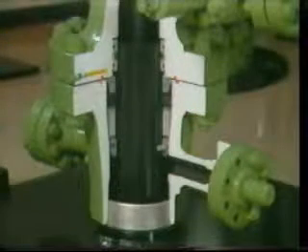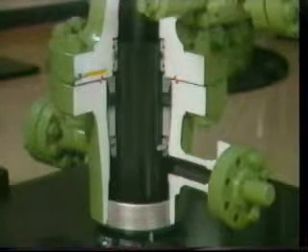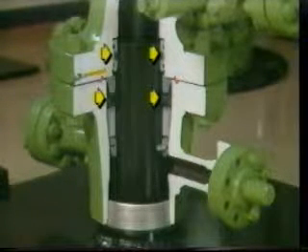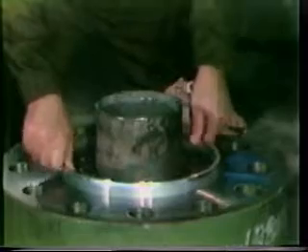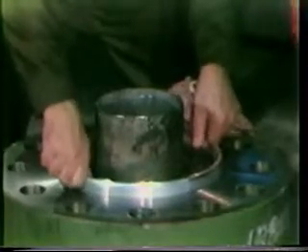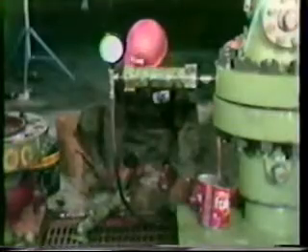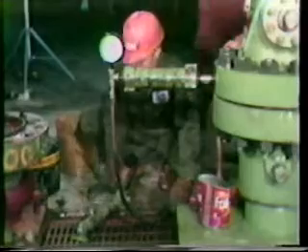The installation of the casing head and spools includes the pack-off of each casing outside diameter and the inside diameter of each wellhead component. The term pack-off generally refers to the seal acting in the bottom bowl or the top bowl above the slips, but can apply to all bowls. A typical pack-off would be an O-ring located in grooves in the lower bowl. These seals are effective due to the dimensions of the seal and to extrusion of the sealing element when pressure is applied. Some seals can be activated by injecting plastic into the ports located on the casing spool.